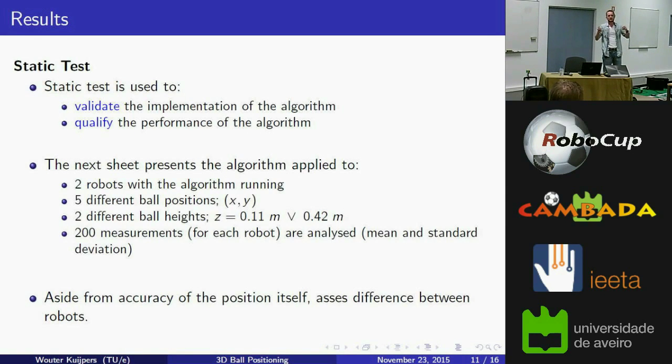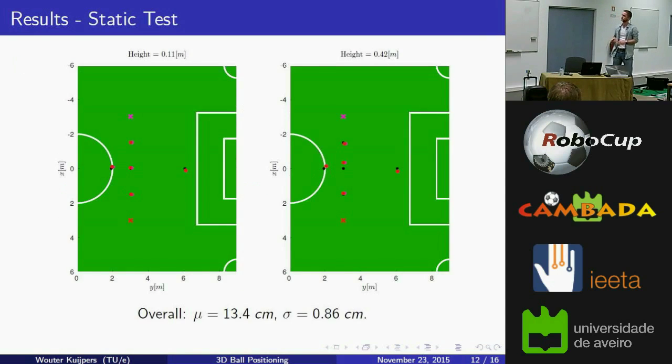But for example, the data from robot 1 is communicated every 1/10 of a second to robot 2. Because the vision runs at 50 Hertz, there could be executions where we don't have the data from the other robot. Of course, the same happens on the other robot, so the algorithms will provide different results.